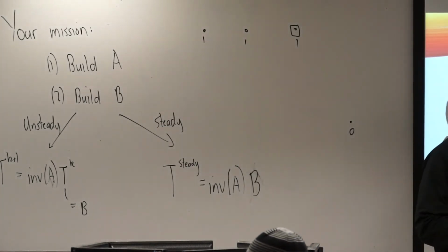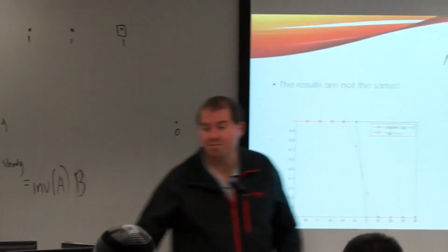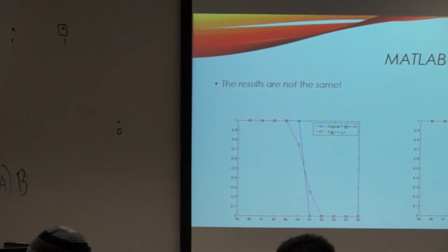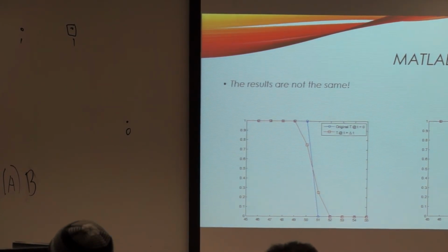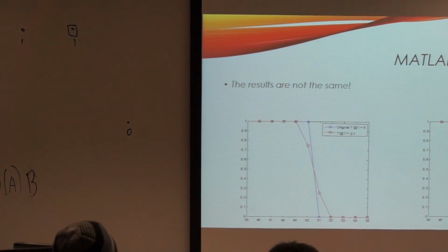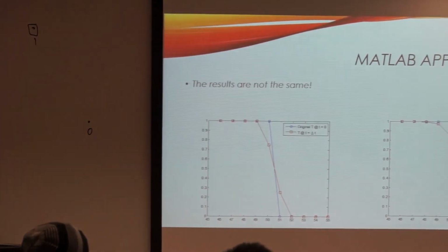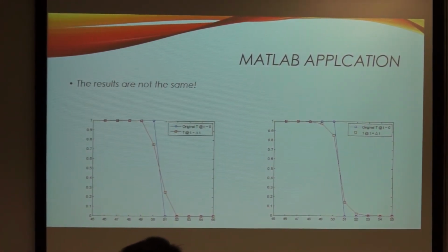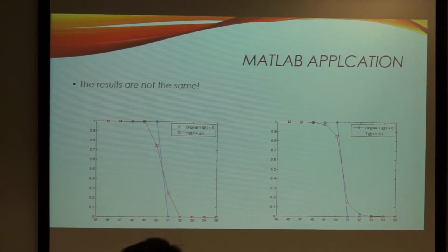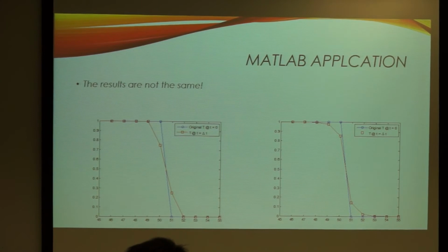But guess what? Implicit, this point here did change. Because it can, because we compute all of the new temperatures at the same time. So we can allow heat to move further in one time step than otherwise might be possible. And that's a pretty neat thing. Now, you might be thinking this is a good thing. It is not a good thing. Sometimes this is called dispersion error. Implicit techniques have an associated dispersion error with them.